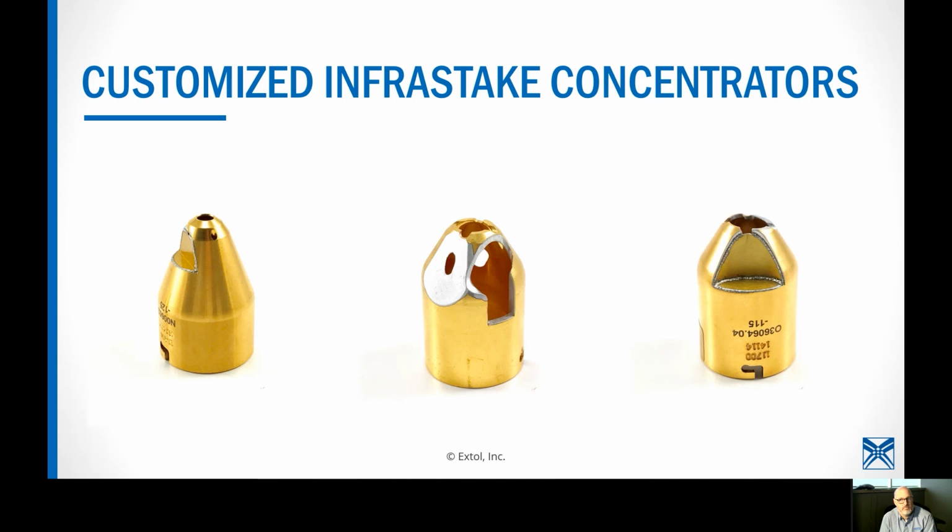PPE requirements, protective equipment. There's a potential for a little bit of off-gassing. I don't see a lot of machines that are vented, but you may want to consider it depending on what you have going on in your shop. The biggest thing is the modules don't get hot enough to be a burn hazard, but there's a pinch hazard, because we're going to be clamping these things together on an end of arm robot. It's not like a thermal punch where this thing's at 600 degrees for 12 hours during the day. It gets cool right down.